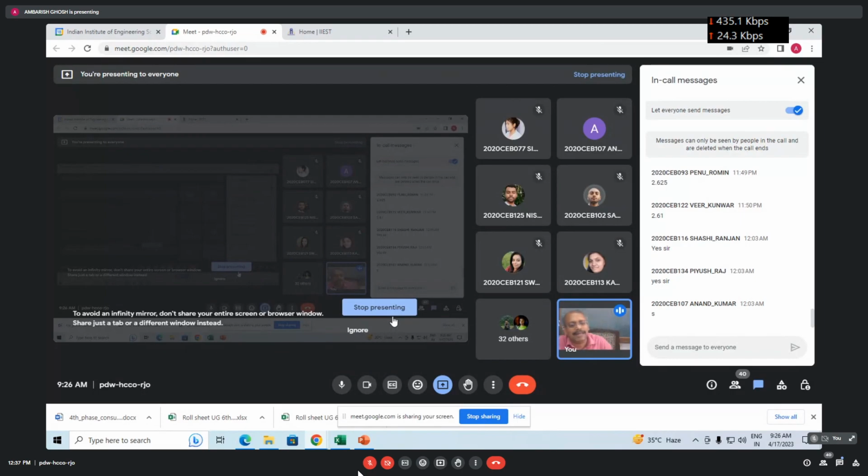If you increase the length, capacity will increase. Sometimes this is not true. Suppose a pile is resting on sand and immediately below it is clay. If you put it in clay, even by increasing the length you may get less capacity. This is the engineering judgment basically you have to do. Where the pile should rest and what should be the length, that you have to decide.